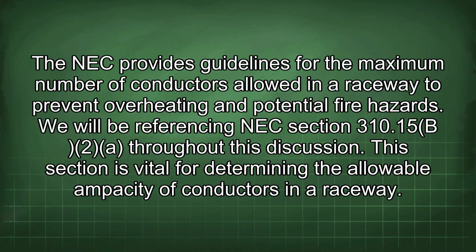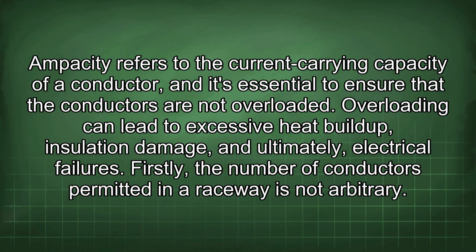310.15(B)(2) throughout this discussion. This section is vital for determining the allowable ampacity of conductors in a raceway. Ampacity refers to the current-carrying capacity of a conductor, and is essential to ensure that the conductors are not overloaded. Overloading can lead to excessive heat buildup, insulation damage, and ultimately electrical failures.